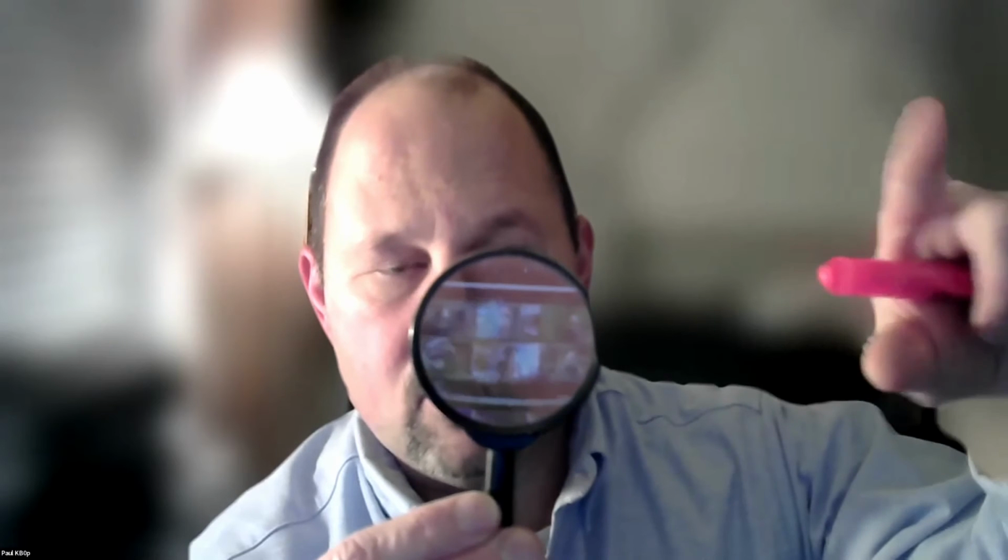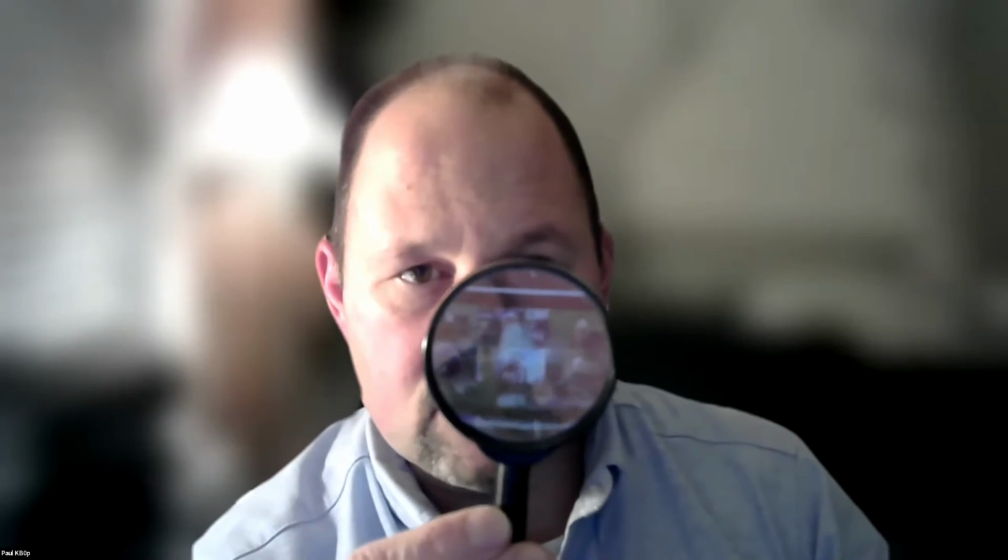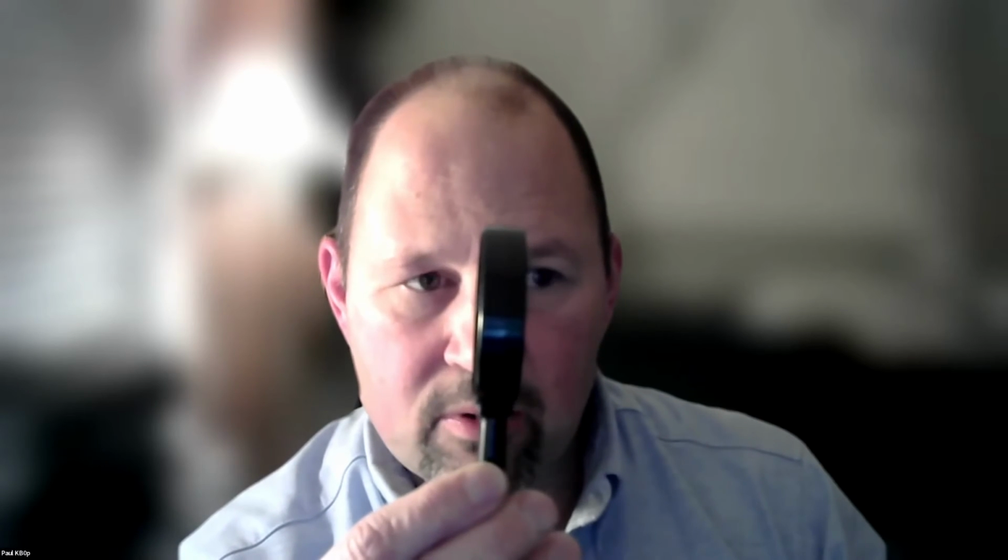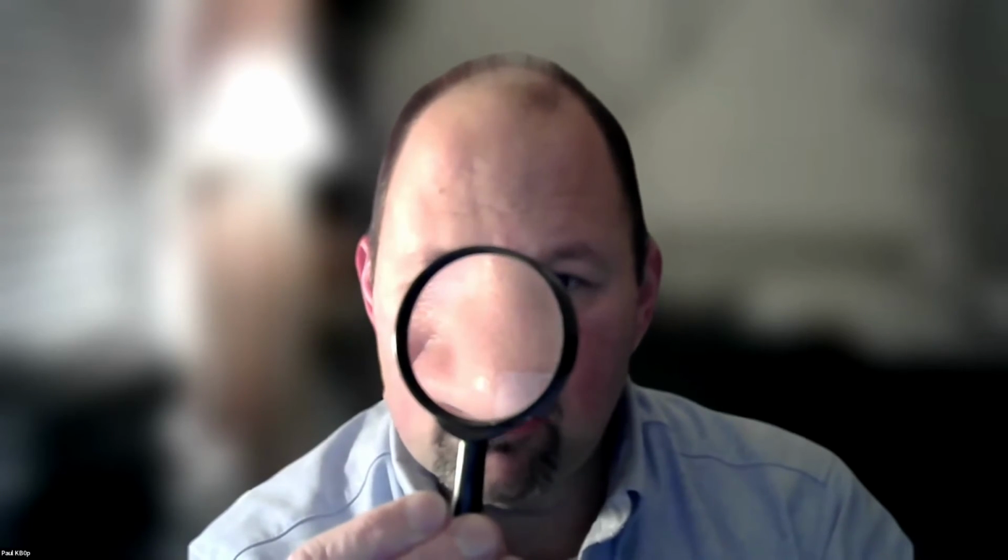If I'm receiving a station from, say, Chicago, and I'm in Green Bay, Wisconsin, so Chicago's south of me, I would have to turn my antenna so it's facing north and south in order to pick up that station. I can pick it up like this, but when I turn my antenna like this, it gets much, much, much stronger. Now, do I know if that signal's coming from the south or the north? No, because it's receiving off both sides. But I just know where Chicago is. And if I spin my antenna east to west, I will pick up east to west signals better. So that's what I found with mine.